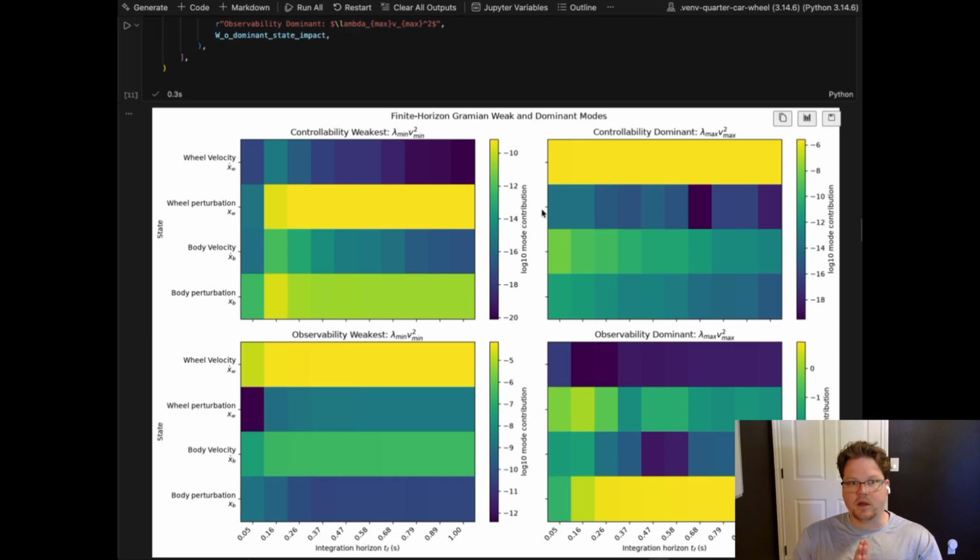Well, sorry, just to back up, it's the wheel perturbation. So we have integrating that velocity component, and also we have the tire stiffness spring. So we have that component as well, and basically additional couplings here that make it harder to control that wheel perturbation itself.